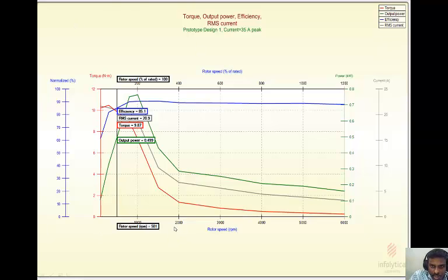So this is the chart. It is going to explain the entire story of the designed machine. The advantage is you can have this chart together with the voltage graph, stress plot, everything all together. Only for more clarity, I included four different outputs with respect to the speed, that is torque, output power, efficiency, and RMS current. This side two and this side two. That's it.